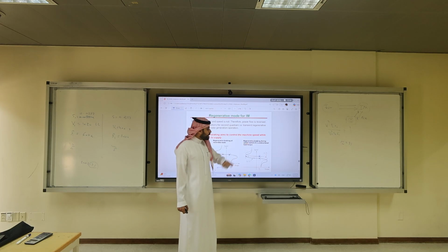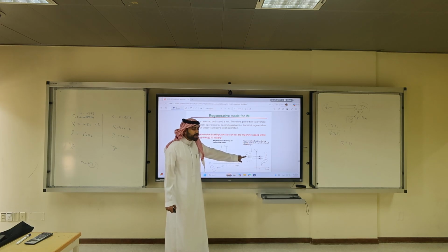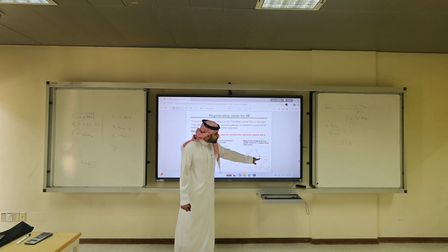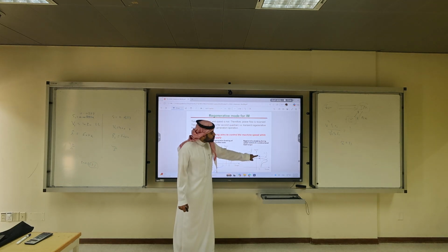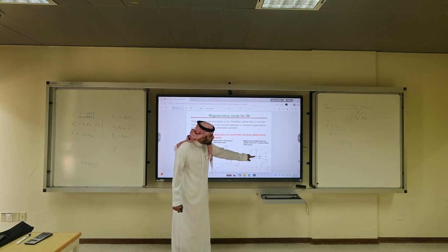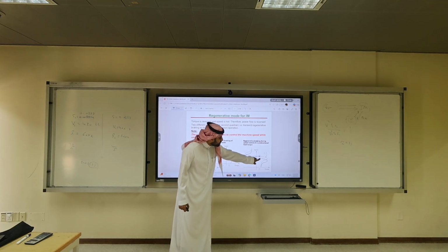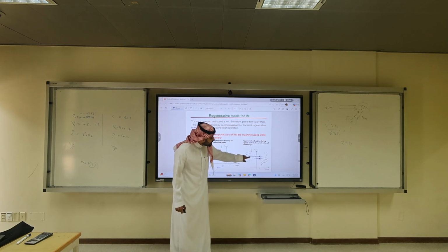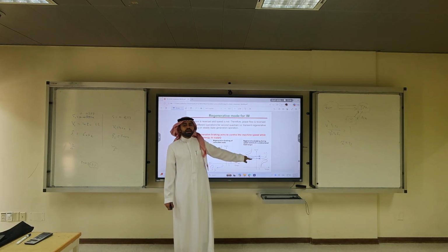I have to change all my capability curve, and then I will find another intersection here that drives me back to point number 3. So during the transient of time, remember this will take very quick time, I will experience a little bit of regenerative braking.